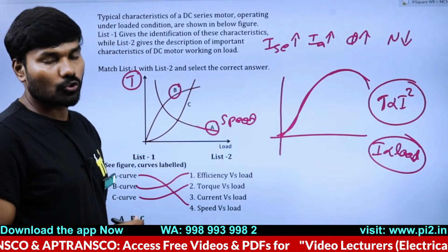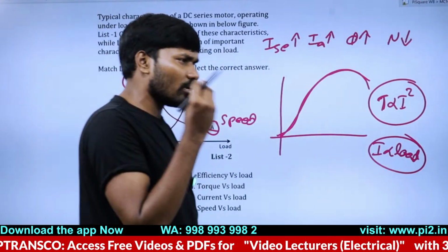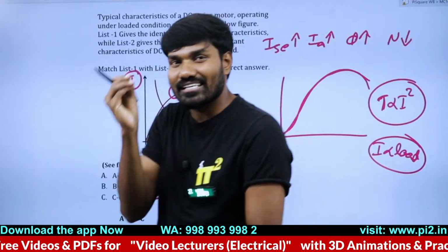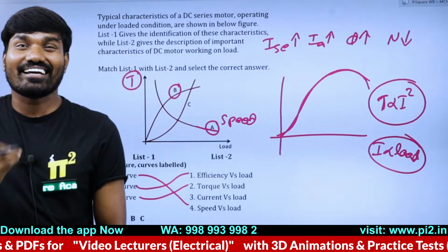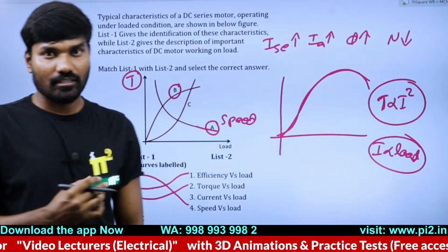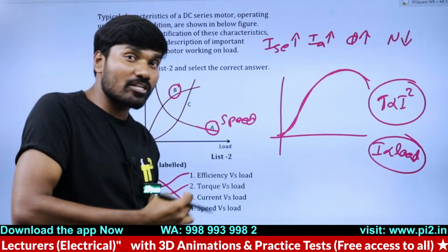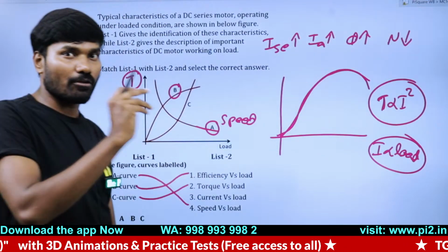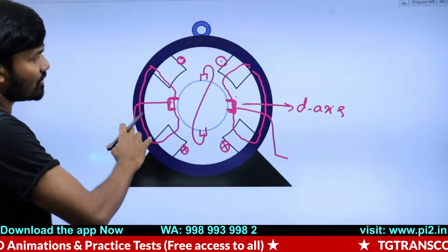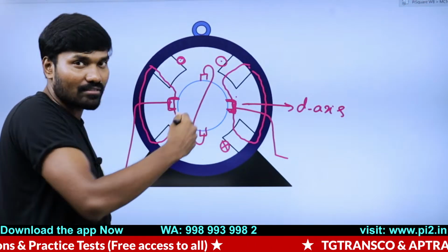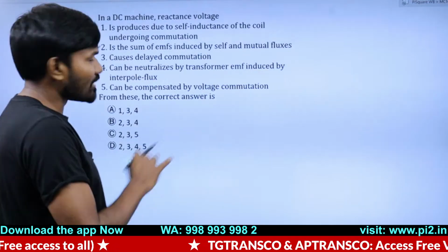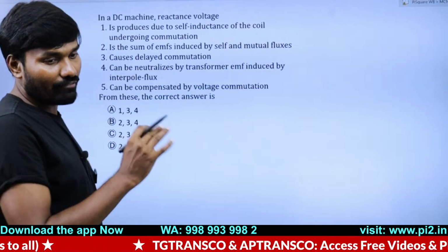Yes, Praveen Kumar, 2 brushes are sufficient. Only 2 brushes we'll use, not 4 brushes. But the 2 brushes will be short circuited. That's how you're creating the cross field. To create a cross field, the armature also gives some magnetic field. I think when you understand cross field magnetization, you will understand this. Short circuiting will help us in creating a field also. That's a good, very valid question, dear.